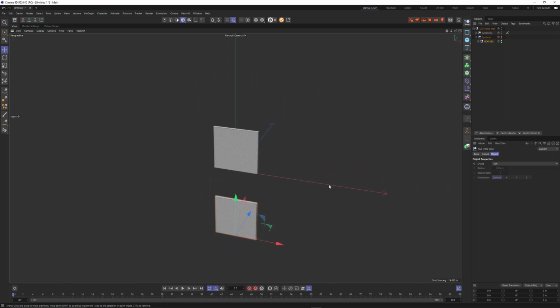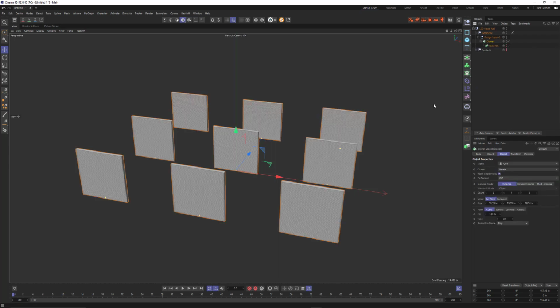So now to build a wall, we're going to hide this again. We don't need this. All we really care about is the instance. This is what we want here. So we've got this guy. So now this we could put into a cloner. See how all the tutorials now are starting to come together. Let's throw this into a cloner. So I'm just going to hold down the Alt key with this selected, and I'm going to click on cloner.